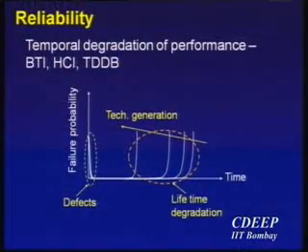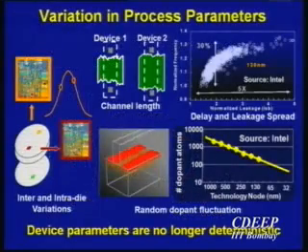So let's look at, for example, a 32 nanometer technology, and you look at some devices which might be longer than some other devices coming from a different wafer lot. So the width of the devices can vary, the length of the devices can vary, the flat band voltage of the devices can vary, and the oxide thickness can vary. All these, in general, people lump into a threshold voltage variation. Okay? A few other things also turn out to be important: these are die-to-die variations, and more or less systematic die-to-die variations. But there are other kinds of variations that are very, very important. So if you look at a 65 nanometer transistor, you can almost count the number of dopants in the channel, right?